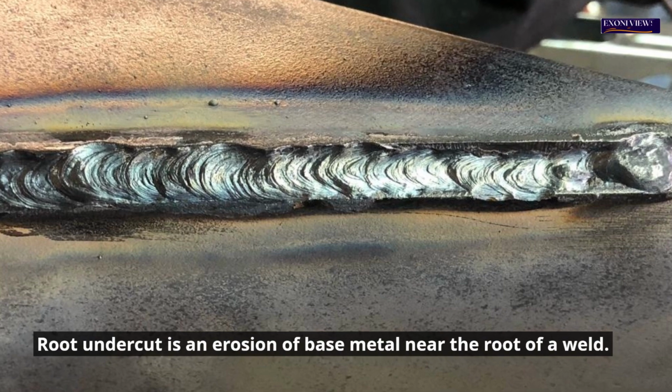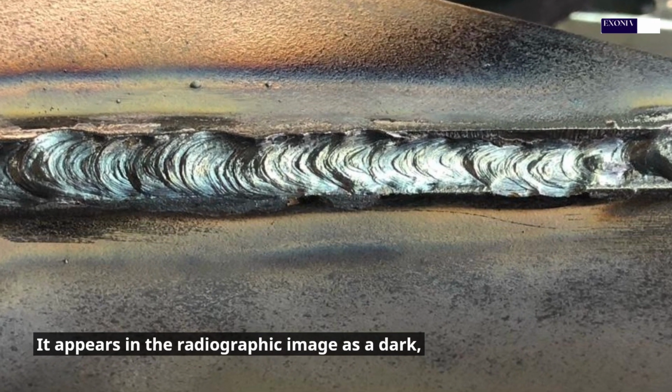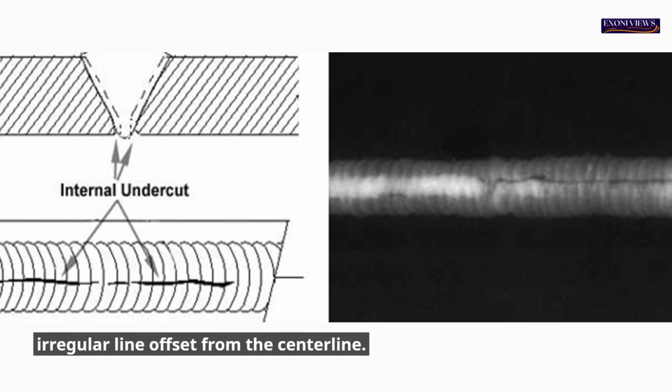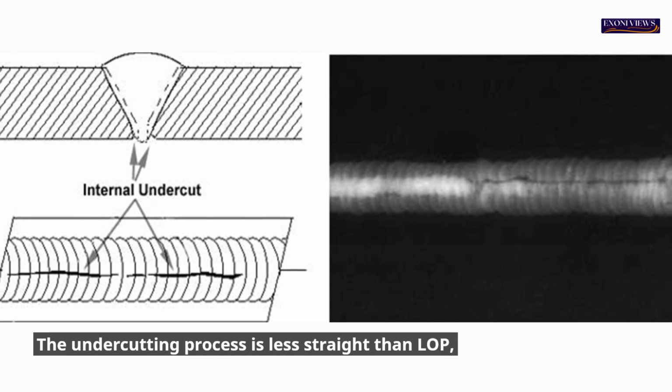Root undercut is an erosion of base metal near the root of a weld. It appears in the radiographic image as a dark, irregular line offset from the center line. The undercutting process is less straight than LOP, as it does not follow the ground edge.